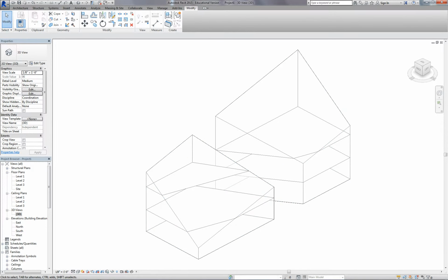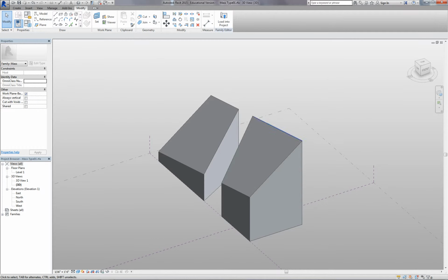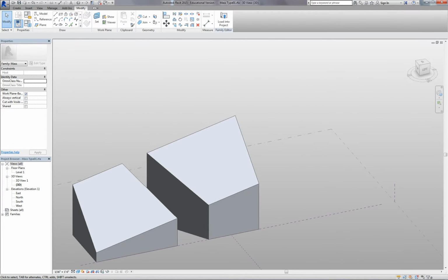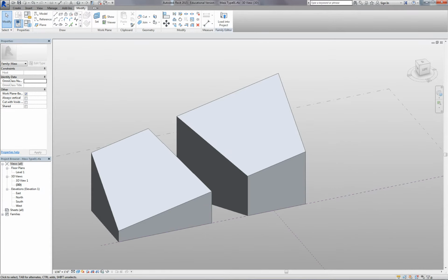So this will allow us to massage, and it's actually nice to maybe have it in a different file. It's referenced somewhere else, so I think it's easier to edit the geometry as a conceptual mass, and we can do other things. We can start adding, like I showed you, the facades, but we can do so many other things, like make structures. Even in conceptual mass, we can do some pretty elaborate geometries that get transferred as real geometry.